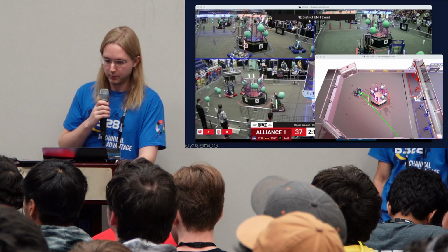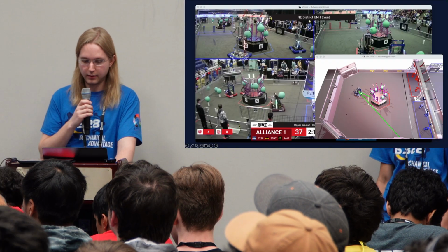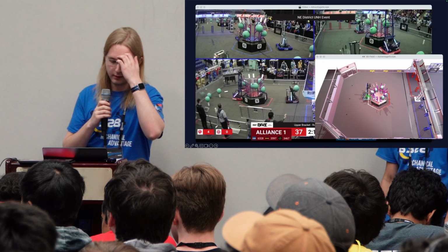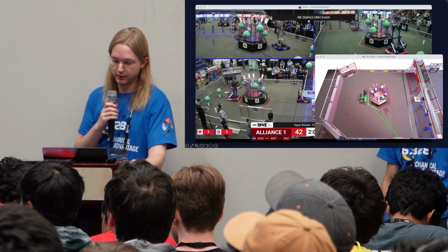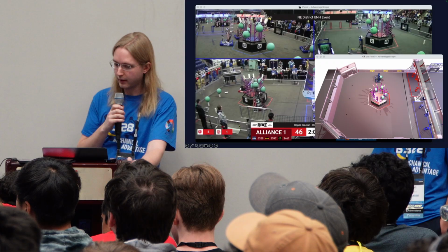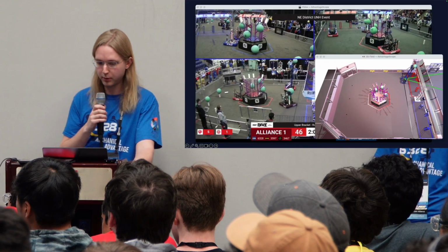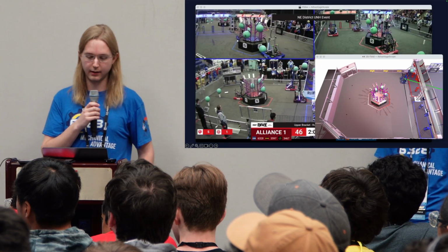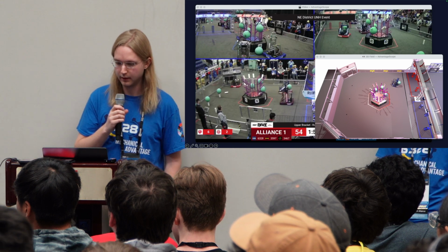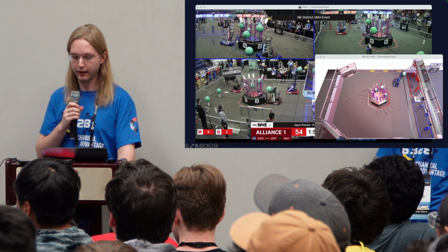So what was happening with the localization data? Well, you can see that visualized to the right, and we're going to replay here. So the ghost robots, the transparent robots, are the individual pose estimates from the cameras. We don't see any tags during this section, and then as we approach the net, we are actually seeing some tags. It's just that it's not updating the estimated pose quickly enough, even though the estimates are quite accurate.